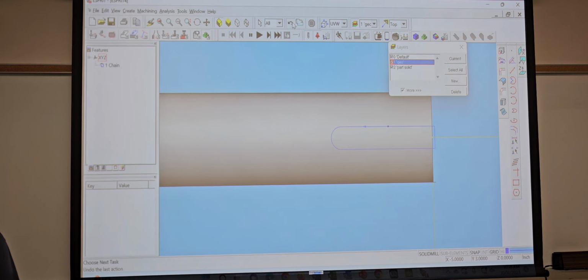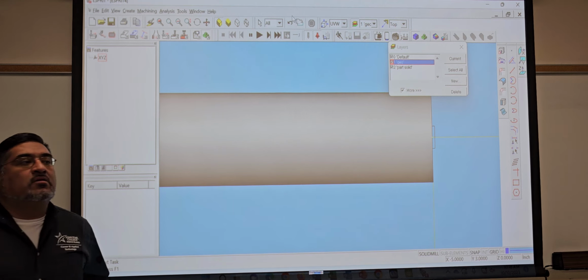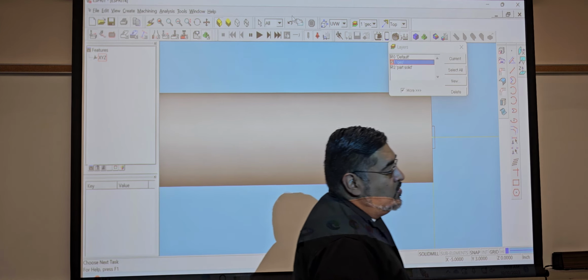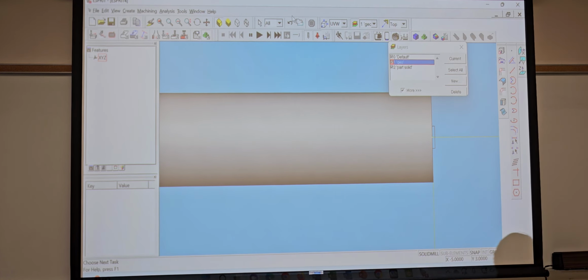So let me ask you this, the difference between pocketing and contouring is where your piece is gonna start the cut, right? Yes and no, but the main thing is knowing what a pocket is. You've got this piece, aluminum or whatever, sitting in your chuck in your lathe. Would it be better to start from the end and come in, or start onto the piece? It depends on the situation, but if I was doing this in real life and I was chucking and I only had the slots out, I'd come from outside of the part and go in. And that's what the contouring will give you.